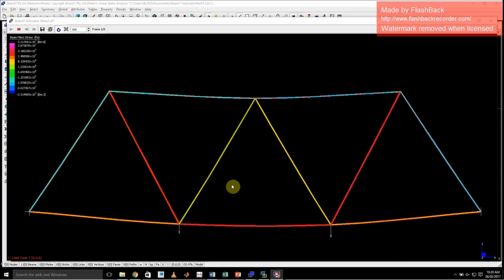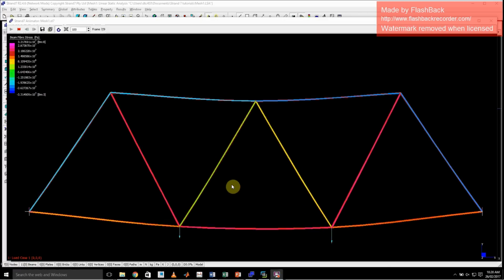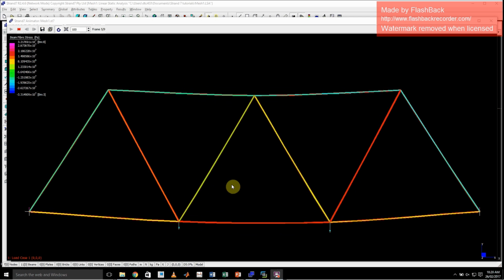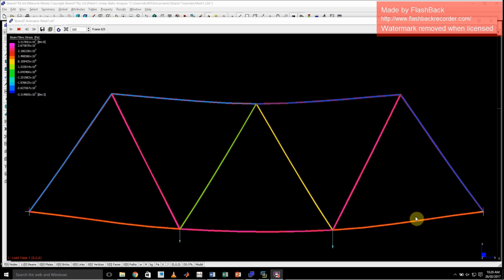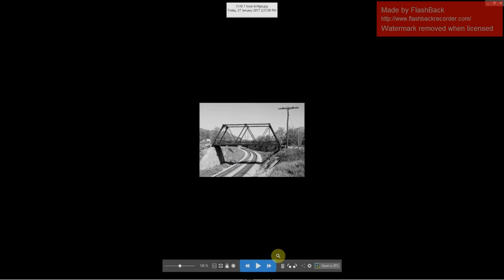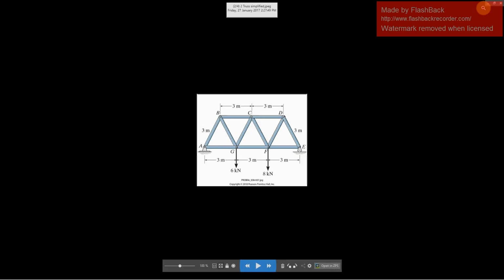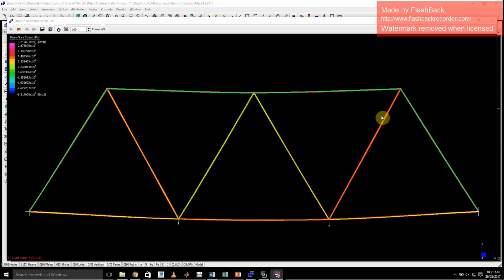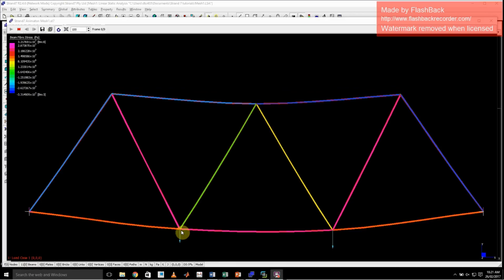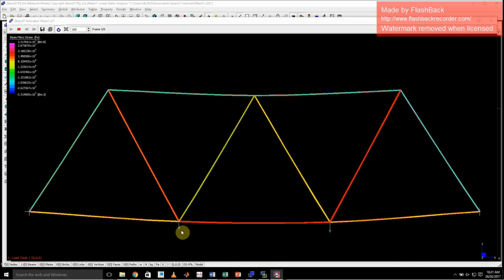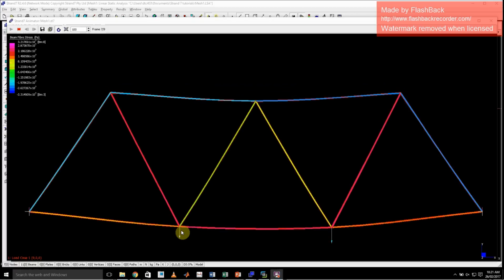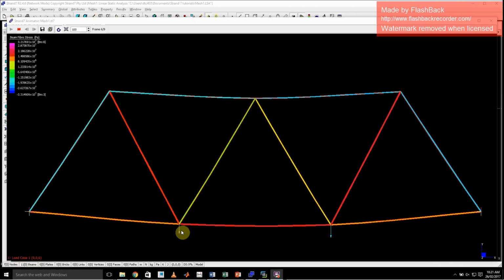The software I'm going to show you is the Strand 7 package. It's what's called a finite element analysis package. What it allows us to do is make a model of our structure. I've modeled a very simple bridge here. So here's my bridge. I've got my model of my bridge, and then I've gone and made it in Strand 7. I've put my loads on it, put my forces on it, and I can watch the way that it deforms under these loads and the way that the stress gets applied in the structure.